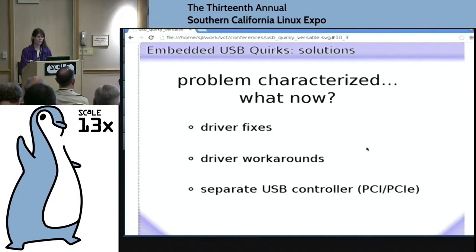And that is actually how the case of the frustrating printer got solved. It was, well, don't plug it into that port. Plug it into this other port over here. Voila, on a different controller. Because what driver workaround can you do when the thing that makes the target unhappy is electrical noise or something that's going on as you're dying from the power outage, right? The managers always want a software fix. How can you do that?